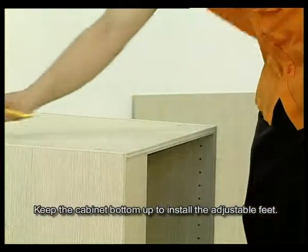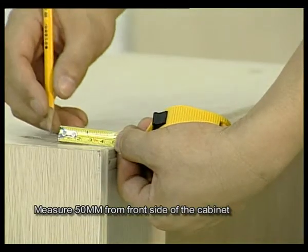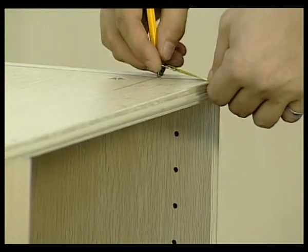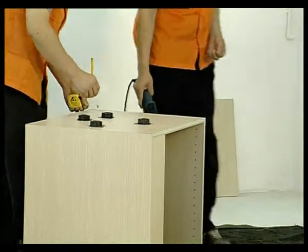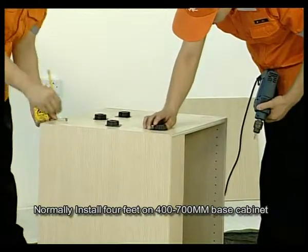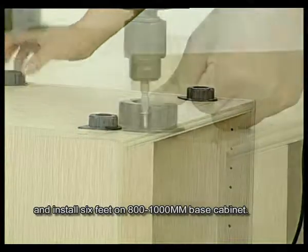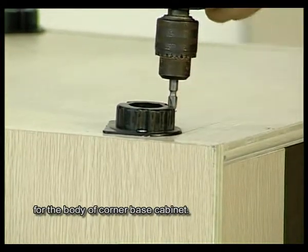Keep the cabinet bottom up to install the adjustable feet. Measure 50 mm from front sides of the cabinet to mark the line and install the cabinet feet. Normally, install 4 feet on 400 to 700 mm base cabinet. Install 6 feet on 800 to 1000 mm base cabinet. Hereby, we have finished the assembly for the body of corner base cabinet.